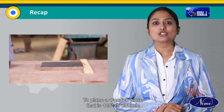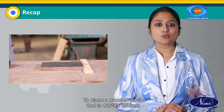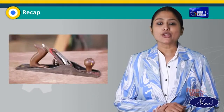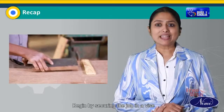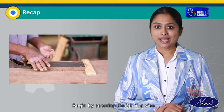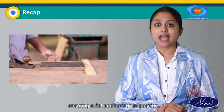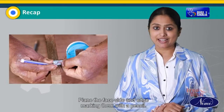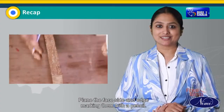Recap. To plane a wooden piece that is 120 by 25 by 250 mm, use a jack plane. Begin by securing the job in a vise, ensuring a flat and horizontal position. Plane the face side and edge, marking them with a pencil.